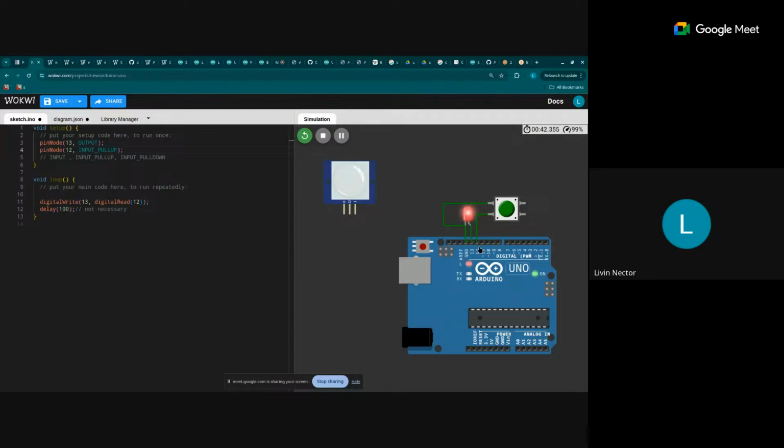So that's the idea, which means setting to pull-up mode configures the internal circuitry to make a high signal, which means by default pin 12 will be set to high. There will be a voltage there, as if there is an internal voltage source. And here this is ground, right? So what happens when you close the circuit?